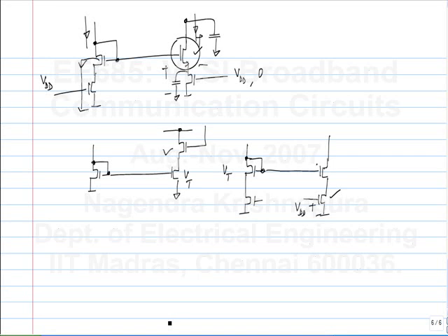Yeah. So that actually further worsens this, right? Sorry, not this one, this. So the VT of this is more than the VT of this one, isn't it? So this is M switch here and this is M switch here. So the VT of this transistor is more than the VT of this transistor. So this will be much worse. In fact, even without considering body effect, it's worse because VGS itself is smaller. In addition to that, the VT of this is more than the VT of this. So VGS minus VT for this, which is what determines the resistance of the MOSFET, is much worse.